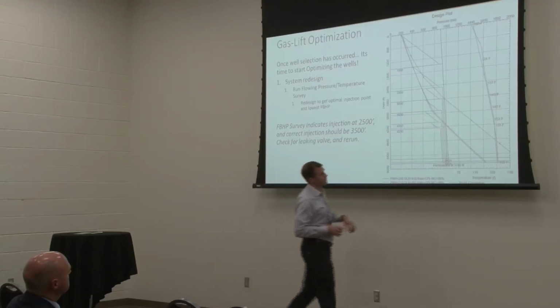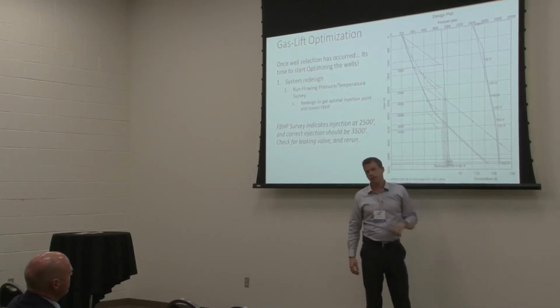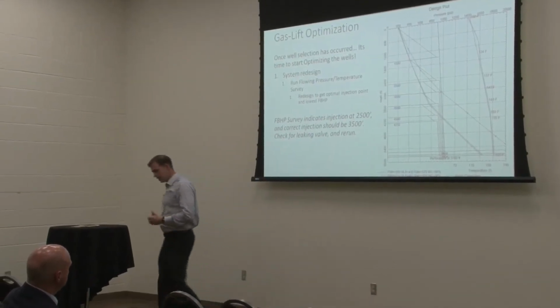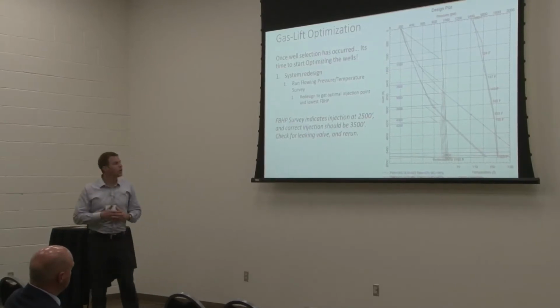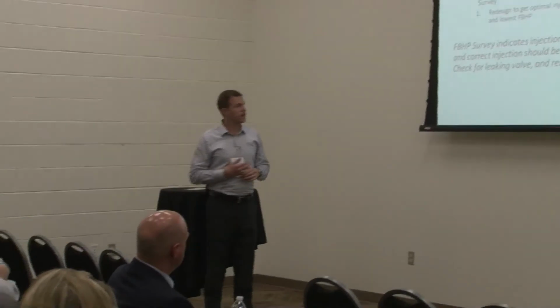And this differential, this change in bottom hole pressure, illustrates a production increase. So this example here would increase our total production and would extend the life of the well on a gas lift system just by a redesign.